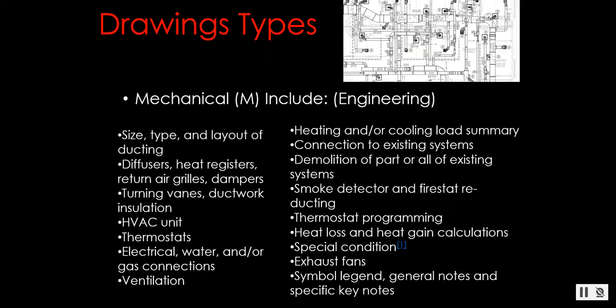And it's important for us to understand how to read some of these mechanical drawings, because what's happening in the ceiling, all these air vents, air ducts, and those things, will be reflected in our reflective ceiling plan. If you have a big air duct in the ceiling, you certainly don't want to put a fluorescent light on top. So as you develop in your skill set and in the program, you're going to learn a little bit more about what some of these drawings are and how they affect our design and how we have to coordinate together.